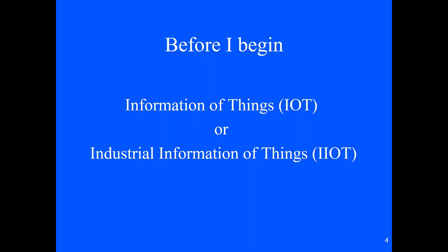One of our suppliers is GE Multilin. They've actually added electrical signature analysis to motors now, and you can get all this data back. I can see eccentricity in a motor. I can see a soft foot. I can see bearing misalignment. So there's a ton of stuff that this IoT has given us now, and all of this gets back to, you have to have communications.